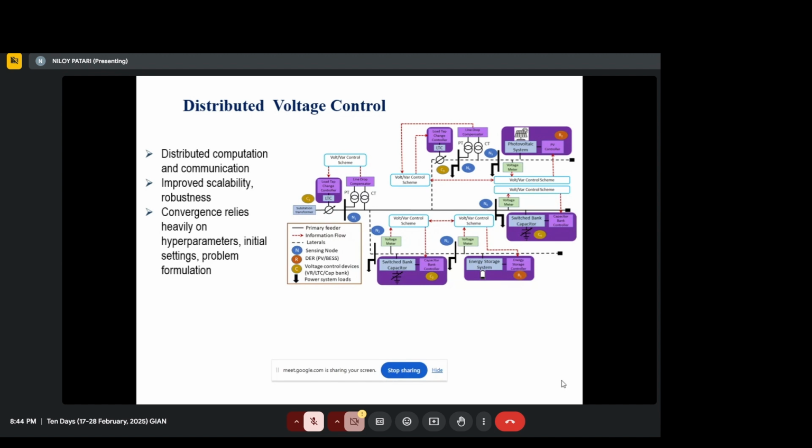Each capacitor bank was say 100 kVAr. So initially it was giving 300 kVAr. When you switch off one, if the set point says to switch off 1 bank, then now you're giving 200 kVAr, right? So these kinds of set points can change, and if the capacitor banks which are on are changed, then the voltage will also change in the next instant.